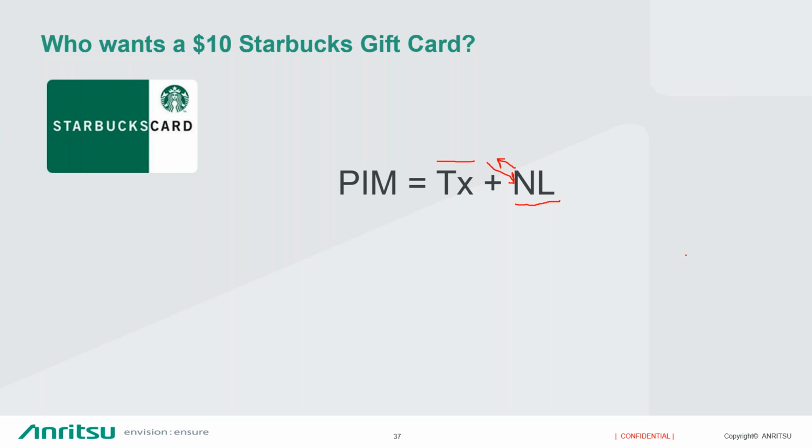What's my CPRI rate? Sometimes you can't get that, either because the information isn't available, or you have to go to the tower and look, and it looks like single mode fiber, for example. If you can do that initial assessment, it certainly reduces the amount of time you have to spend at the tower. You have the right fiber and SFPs, so you can plug them into the sensor. You know that you're looking for the 700 megahertz and the 1800, for example, or whatever bands they are, and you at least have an idea of what the tower looks like. I always recommend doing that before going to a site where you're going to plug in something like this.